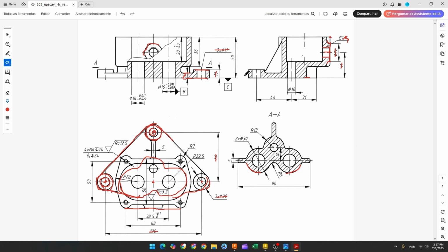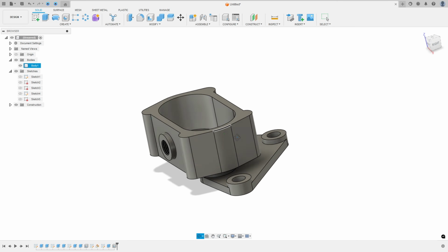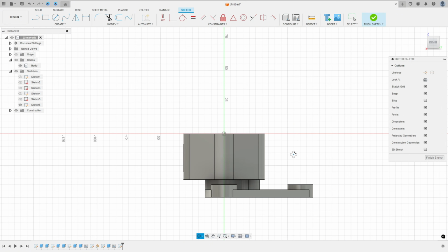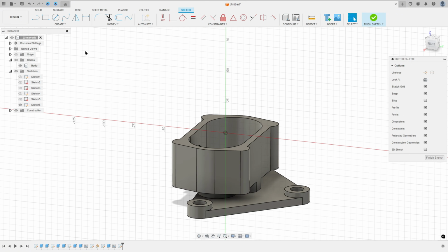Now here, we need to create this rib here. So to create this rib here, the distance between this point and this point here we'll consider 5 millimeters. Okay. So open the Fusion, move this here, go to create a sketch and select the right plane and go to create and select the project included project, select this face here and press OK.